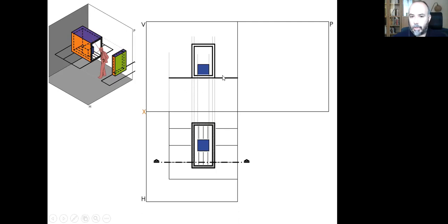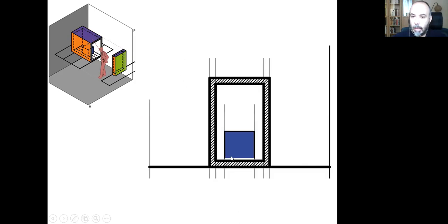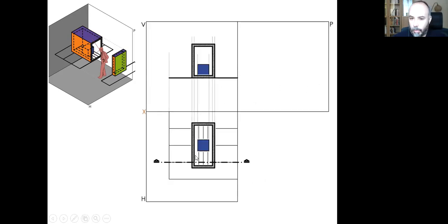And once I finish drawing, I can start coloring. I need to use the same color to indicate the blue cube. And again, I want to effectuate this cut surface. So I am using the same hatch that I used for plan by leaving the same gaps. And again, it's a 45-degree inclined lines.